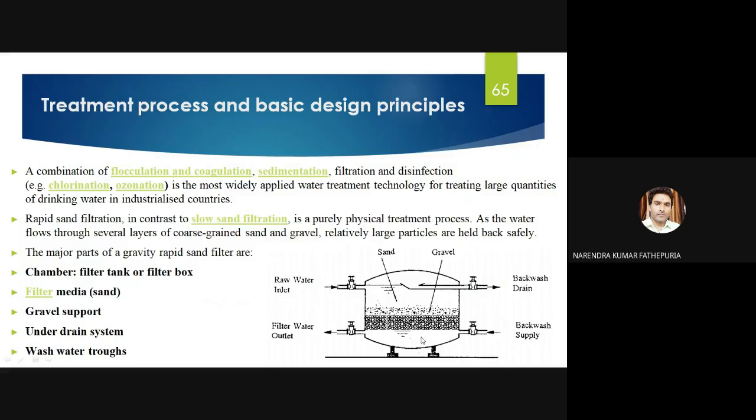Backwashing is required for cleaning these filters. From the bottom, there will be a sprayer mechanism with high pressure jets. Water will be sprayed in these filter beds. So whatever impurities are deposited in the pores, whatever suspended solids or bacterial components are deposited, will be removed, and then finally this dirty water will be sent out for the primary operations. So it's a closed loop actually. The backwash water coming out after cleaning this filter will become dirty. Again, it will be sent for the primary treatment.